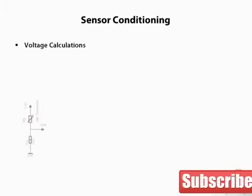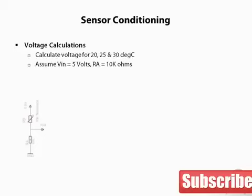Let's calculate the output voltage of our temperature sensing circuit for temperatures of 20 degrees C, 25 degrees C, and 30 degrees C. We'll assume that our process can accept a 0 to 5 volt signal, and we'll select RA equal to 10 k ohms. Using our equation, V out equals V in times RA over RA plus RB.